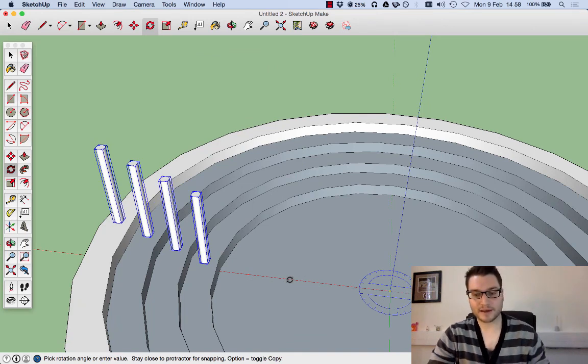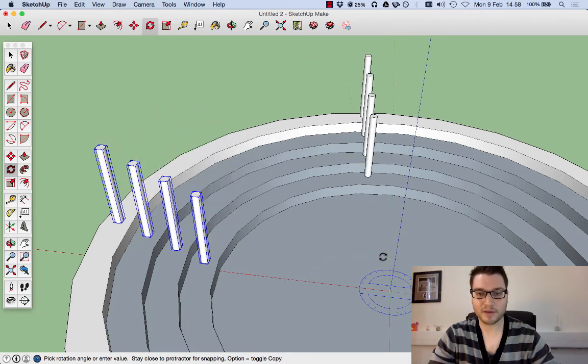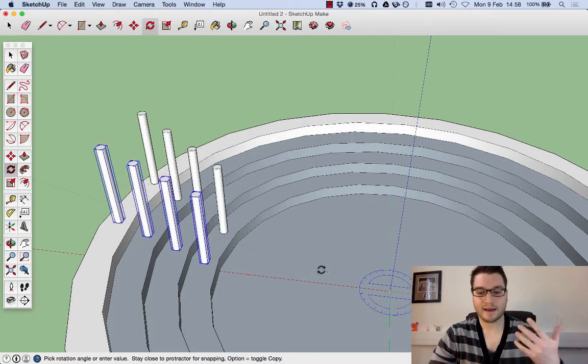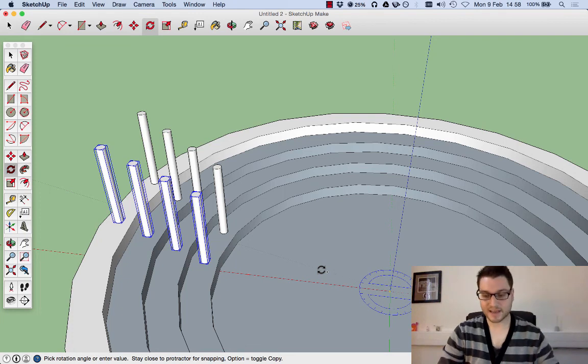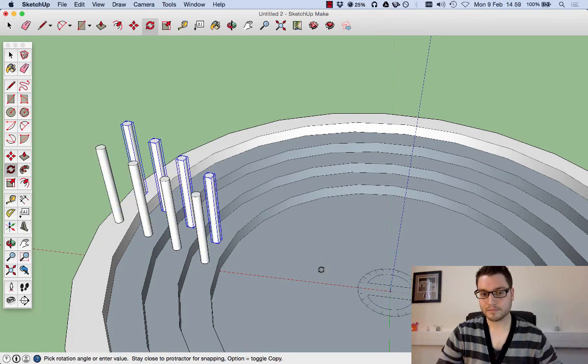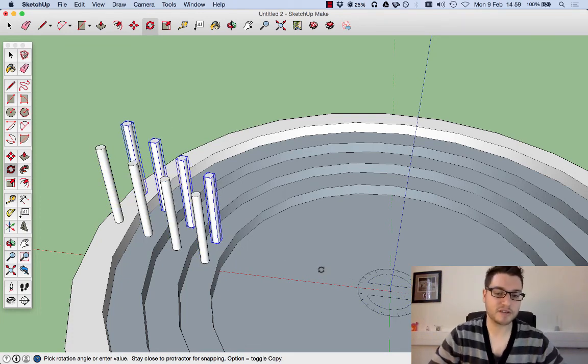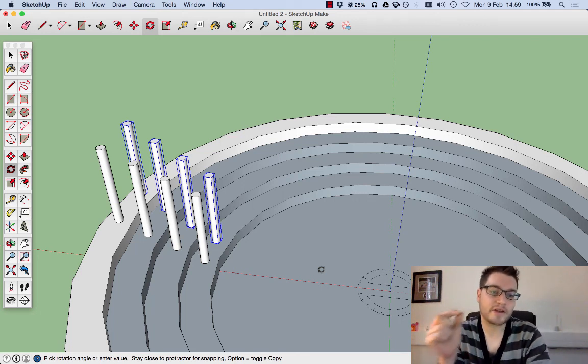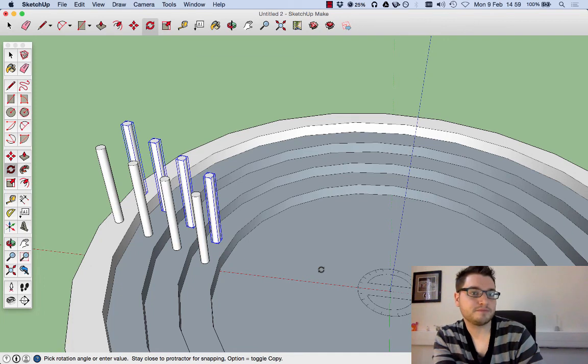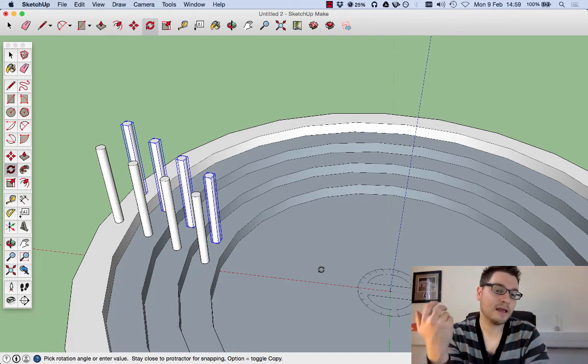And what we do now is we press the command key again, so we're talking about copying. We need to give it an angle. I'm going to say 10 degrees. Okay, so we've done that, 10 degrees. This is where another command is, which says, do this again this many times. Now, obviously a circle has 360 degrees in it.